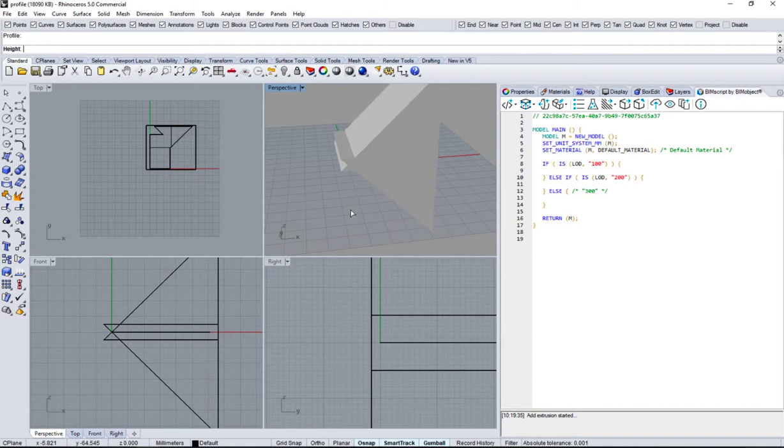And that's very important if you're gonna make it parametric. So if you want to connect a ranged parameter to this profile, you need to define, or you need to remember the default height of this profile. So I'll put 100 because the default height of the profile needs to be higher than both the cutting objects together.